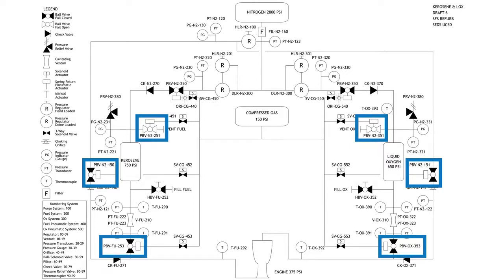And there's a bunch of technical stuff that goes into these valves. There's like seats and seals. So basically, you never have to worry about your ball leaking. Because if this leaks, you'll be sending propellants to your engine when you don't intend to. And you might cause a rapid disassembly of your engine, as the NASA guys would say it.